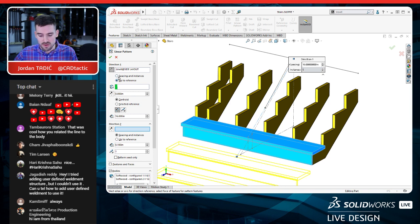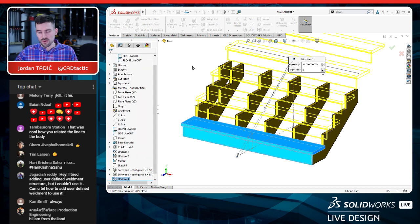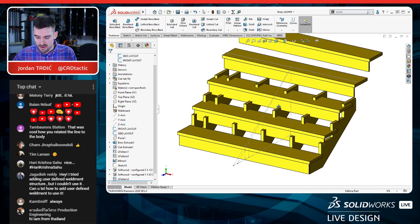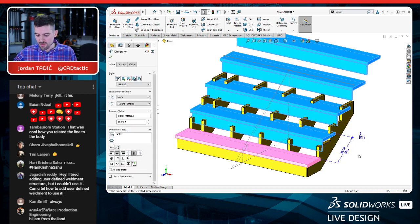And we're not doing up to reference this time. We're going by a specific spacing because we know that spacing from the reference sketch. So let me flip that direction, and we'll just leave it at what it is right now because we're going to right-click on this and link or add an equation. All right, so if I select on the linear pattern, it shows me all the dimensions. They're kind of hidden over here. There's the quantity. There's the spacing.